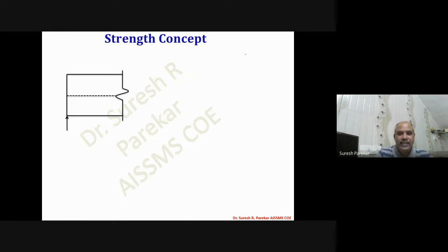Now you can see this. This will be the cable line, and along the cable line we have tension in the tendon, which is equal to P. And then at a distance e, this force will be developed because we have equilibrium, summation Fx = 0 and summation M = 0, and therefore we should have T equal to P and C also equal to P, but both are along the same line. If we have no dead load and no live load, in that case both are along the same line.